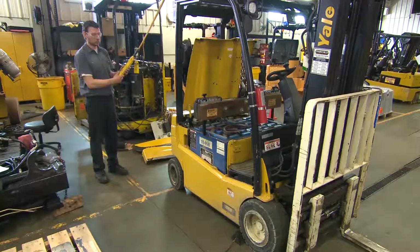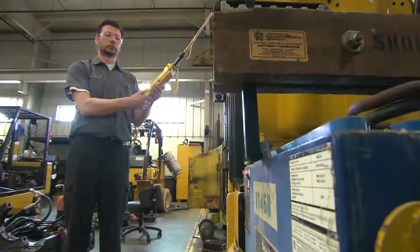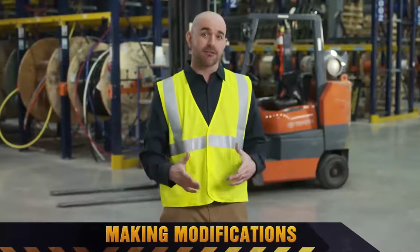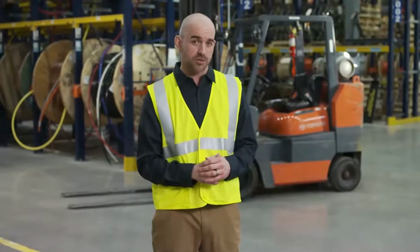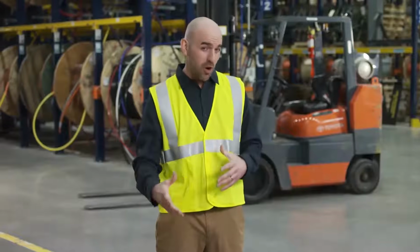Make sure the battery is securely attached to the hoist before lifting it, and stand clear as the battery is moved in and out of position. Any modifications or attachments that affect the safe operation or capacity of a forklift must be approved in writing by the equipment manufacturer. The alterations must be changed on the unit's data plate and printed in the operating instructions so you know how the changes affect the unit's load capacity.